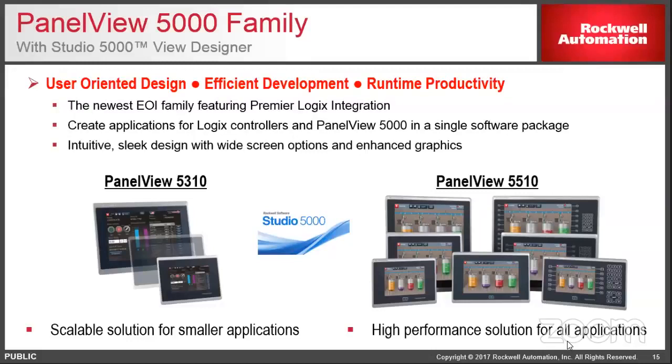But that's a mouthful. At the end of the day, we have hardware that's out today. The 5310, the PanelView 5310, is part of that 5000 number that we love. If you're familiar with PanelView Plus 7 Standard, it's the lower price point model. It's got a couple restrictions on the amount of controllers, the amount of screens, the amount of alarms, so it's for smaller applications. We have a couple screen sizes there. I'll get into the tech specs, but that's been on the market since December of last year. It's a really neat little product, and that's what I have in the demo kit.